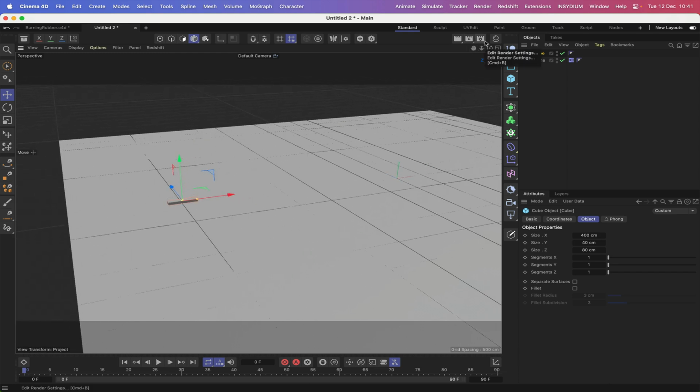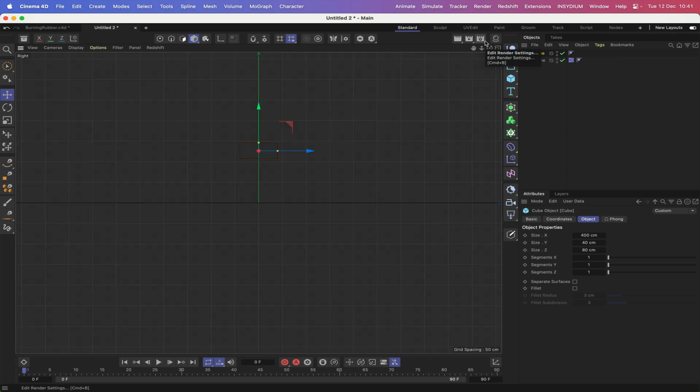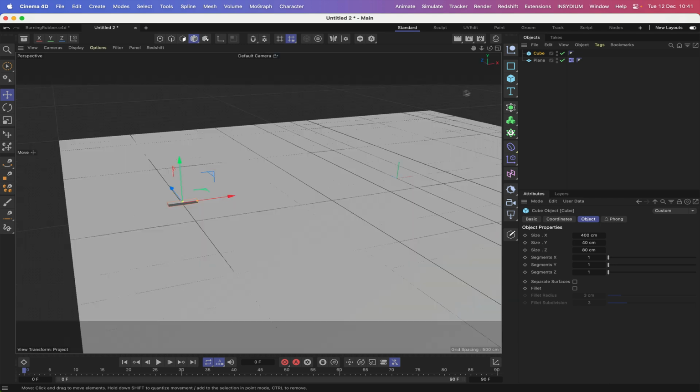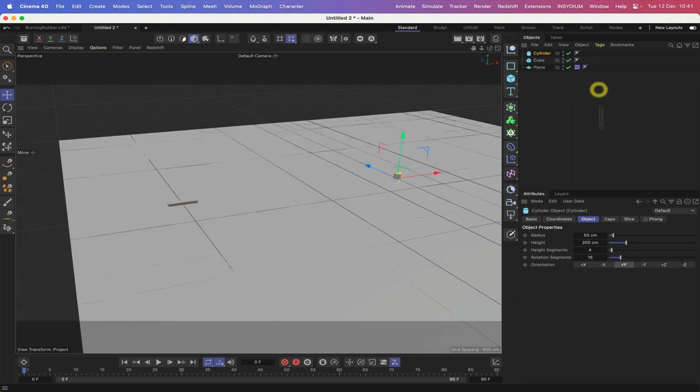We just change to our right-hand view, so F3, see where we are. We can probably drop this down some. Probably drop it down to somewhere around here. Okay. We'll bring in a cylinder object, and the cylinders of course will be used to make the wheels. Our radius we can make 35, so it's about the size of a real car wheel, and 25 for the height.